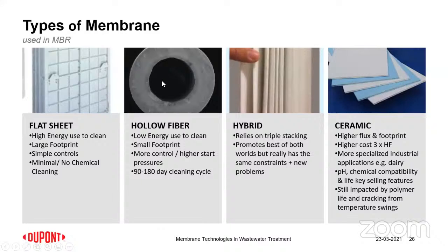Hollow fibers have been used much more than flat sheet, simply because in a unit area you can offer much higher filter area. That is one reason. The second is that flat sheets have the challenge of point defects. If a point on a sheet is damaged, you have to either live with the damaged sheet for a long time, or get rid of one sheet, which means you have lesser filter area available.